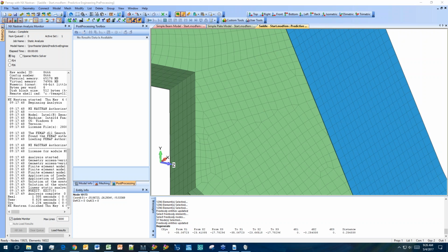Okay, so metal fatigue. I think we got a variety of different, detailed questions, but what I want to do with the last little bit here is just key points. You want to set up the model so you get the right load transfer and the right stiffness, because if your loads are off, everything downstream is going to be off. So that's step one. Step two is realizing that you don't want to chase these singularity stresses at the weld toe. So if you are going to go the stress fatigue route, per the different methods from the different codes, you recover stress either at the weld toe or one thickness away, or the different methods will have different recommendations.